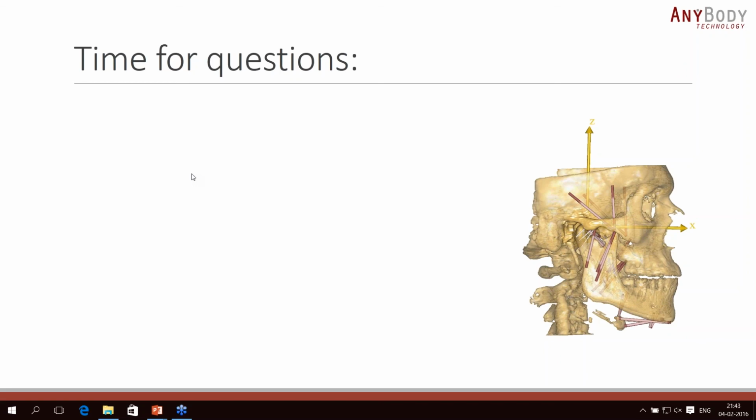Because if you look in the graphs doing these, there's no indication that there's dynamics missing. It's not like there is any of the curves where you look at the measurement and say that it has some dynamic component that must be missing in the simulation. And I think it's because there's a lot of damping in the joint. So if you actually wanted to solve this like a forward dynamics problem, you would have to introduce a lot of damping as well. So then I think you would get close to the same solution one more time.